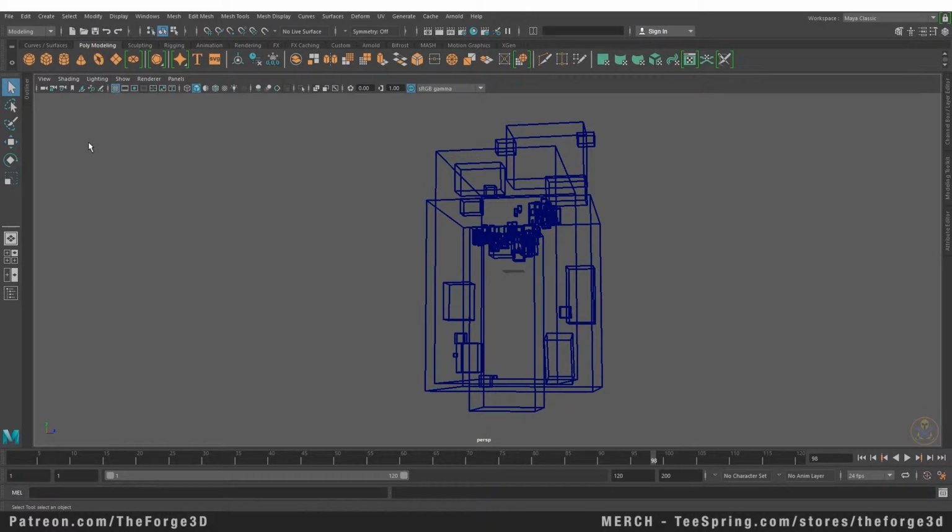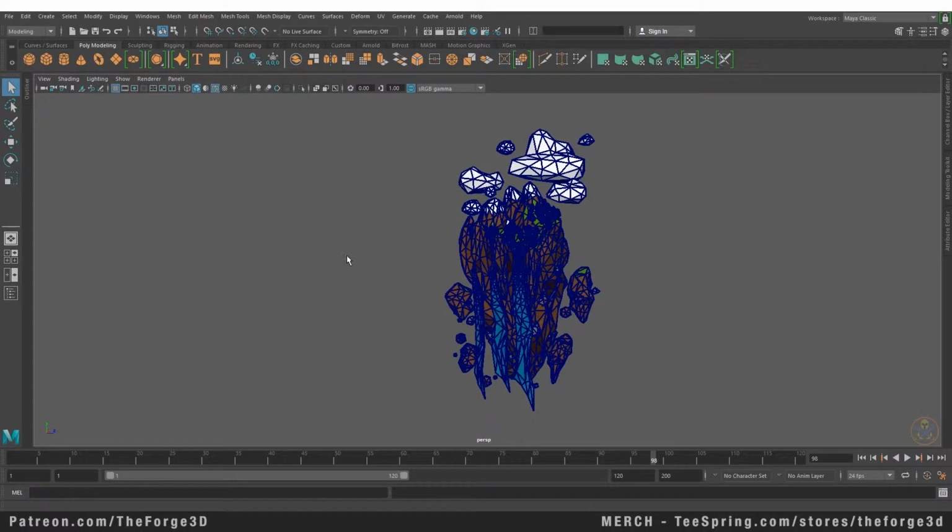If you have a really complex scene, you can turn on the bounding box option and then save the scene. So when you open the scene next time, it will open a little bit faster. So that's a really handy thing when you're working on large projects. After that, you have your wireframe on shaded. It will put the wireframe on top of the shaded object. And after that, you have your X-ray options. In this, you will be able to see through your mesh.